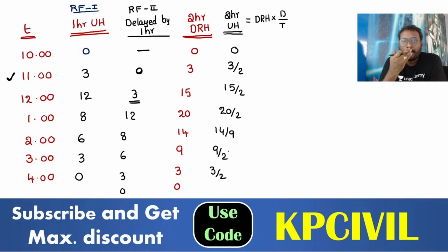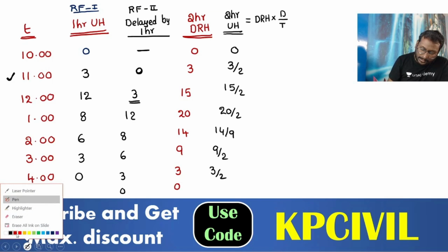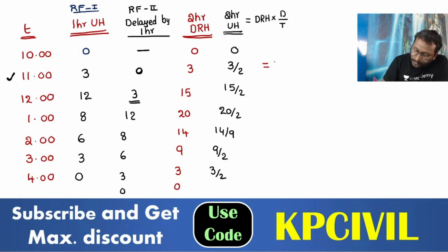Why am I taking 2? Your unit hydrograph provided is 1 hour. Your rainfall that happened is 2 hours. So we are converting 1 hour to 2 hour. D is equal to 1, T is equal to 2, so 1 by 2. So we got the answer now. Here 1.5,